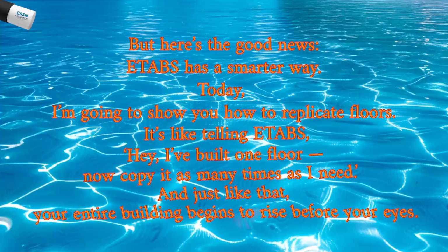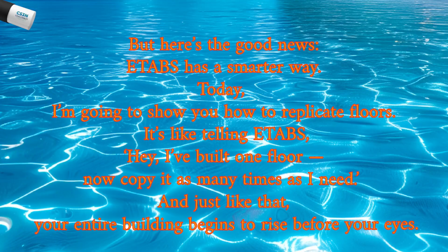But here is the good news. ETABS has a smarter way. Today I'm going to show you how to duplicate floors. It's like telling ETABS, hi, I have built one floor, now copy it as many times as I need. And just like that, your entire building begins to rise before your eyes.